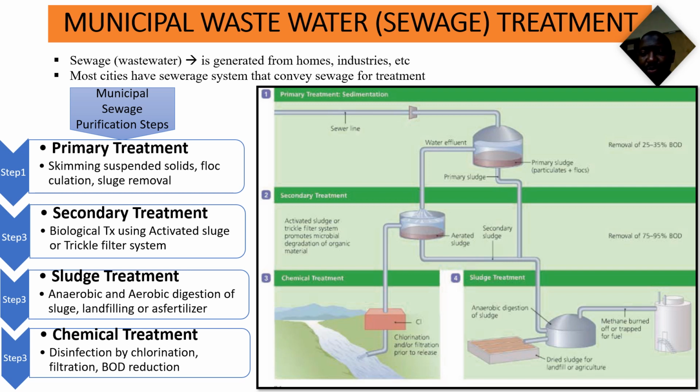Some communities remove the nitrate, phosphate, and any remaining BOD or microorganisms from the water by passing it over fine sand filters or activated charcoal filters. So the nitrate will be converted to ammonia and discharged into the air. And this process roughly removes 50% of the nitrogen content, whereas phosphorus is precipitated using lime or alum, which removes 70% of the phosphorus.